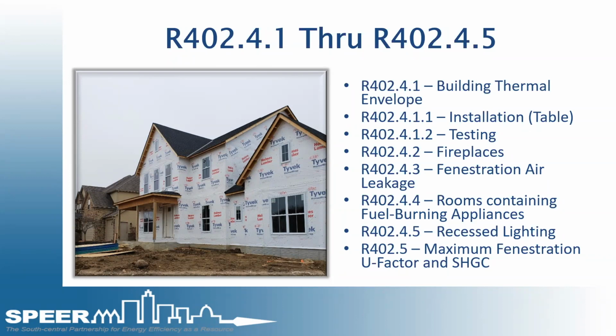It goes to the testing procedures and what the inspector and/or person doing the test can and cannot do during the testing. It addresses fireplaces, which must have tight-fitting doors or tight-fitting dampers and/or doors, and also must have makeup air for combustion. It also deals with air infiltration or fenestration air leakage, showing what the windows can leak up to and having to be certified for that under a certain testing procedure.